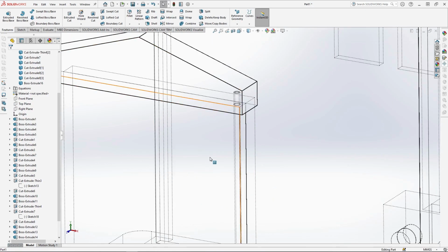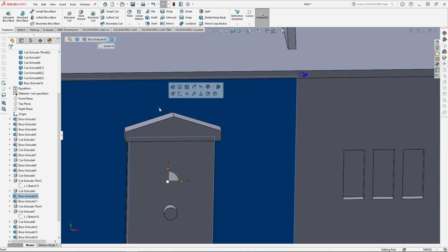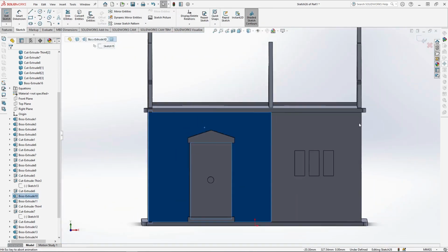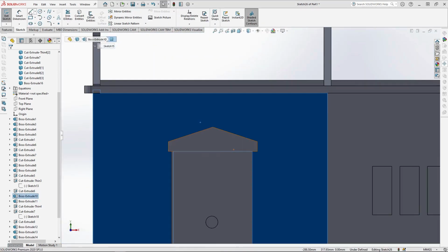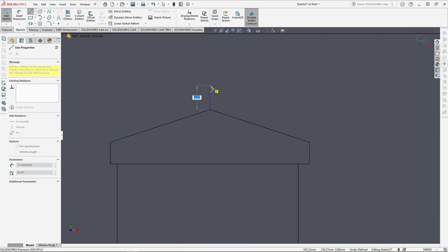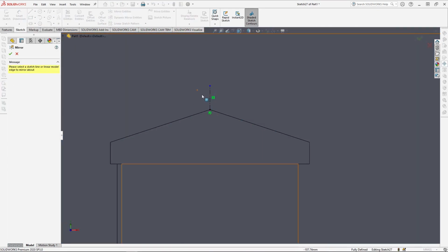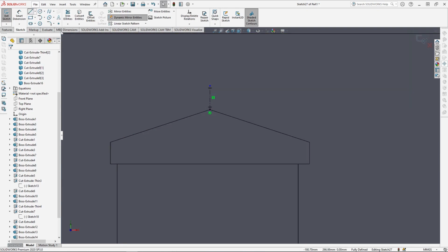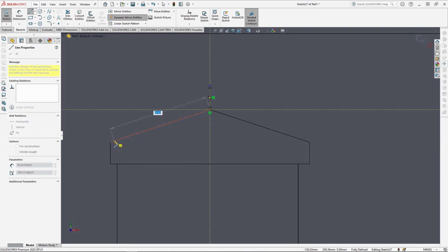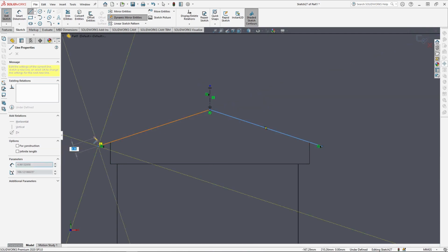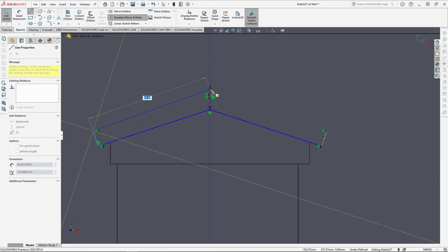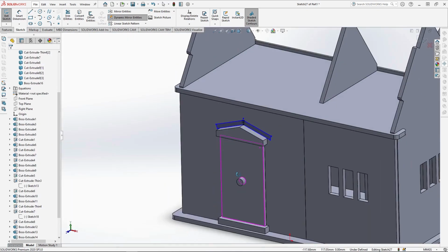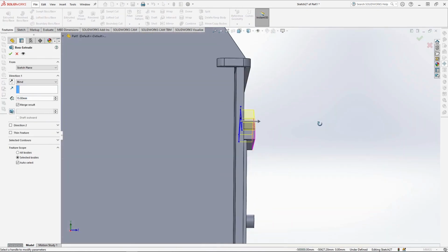To add a roof onto the canopy, sketch onto the large front door and draw a centre line up from the top point. Make sure that it's larger than 12mm. Select dynamic mirror entities, then the guideline. Draw a line from the top of the canopy along the canopy edge here by 65mm, then on the right angle off the line by 9mm. Then go back up along the guide, ensuring that it's parallel to the other. This should create a closed roof profile. Extrude it by 18mm unmerged.